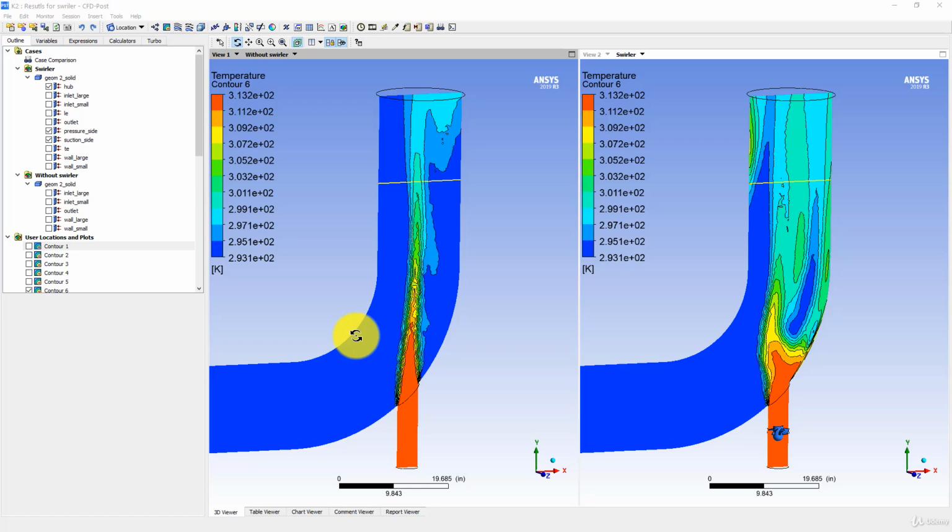For example, on the onset of separation, that mechanism can be turned on and can be turned off when the separation is gone. So the benefit of active control is that the energy will be used only when we need them. But the passive controls are simple to implement, but they have the disadvantage that they will be there forever whether you want them or not.